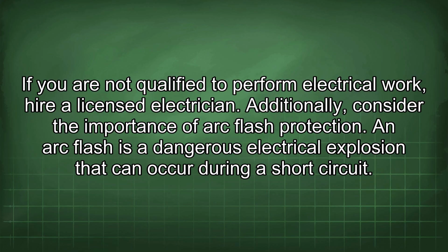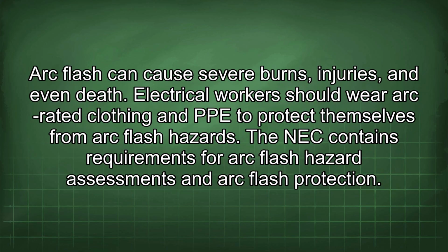Additionally, consider the importance of arc flash protection. An arc flash is a dangerous electrical explosion that can occur during a short circuit. Arc flash can cause severe burns, injuries, and even death. Electrical workers should wear arc-rated clothing and PPE to protect themselves from arc flash hazards. The NEC contains requirements for arc flash hazard assessments and arc flash protection.